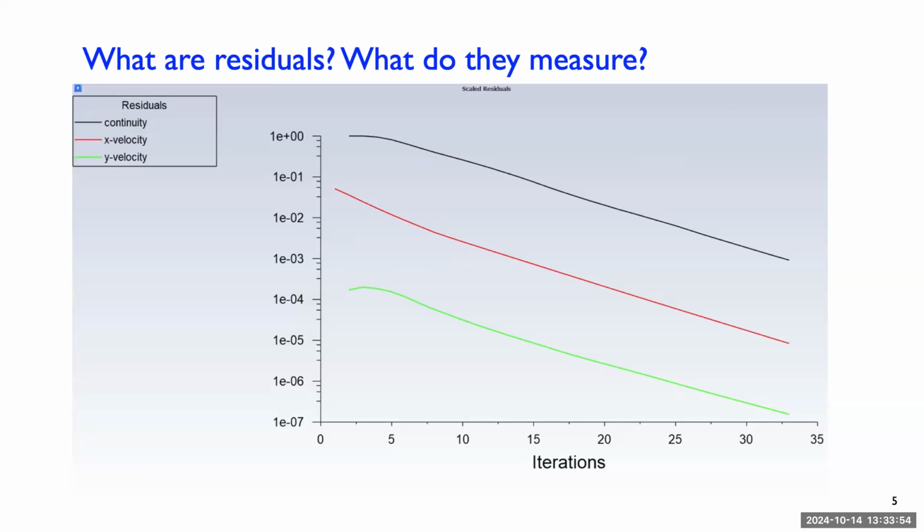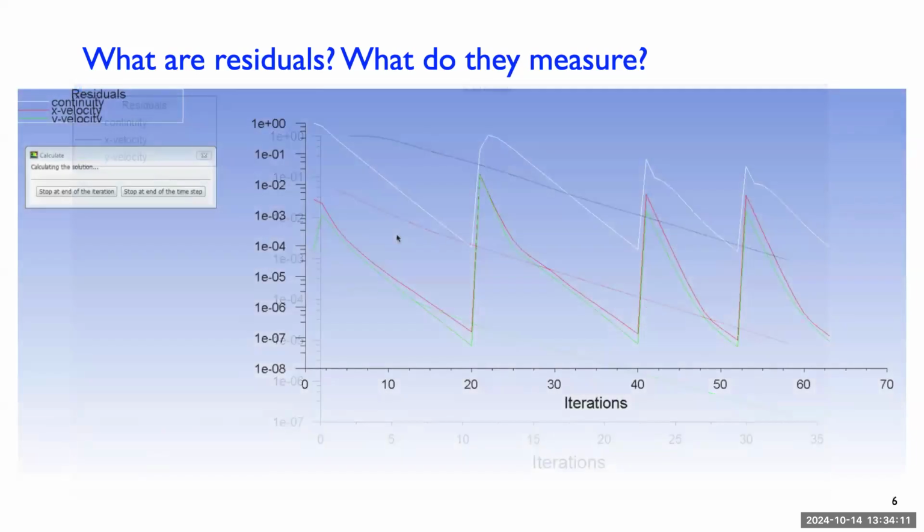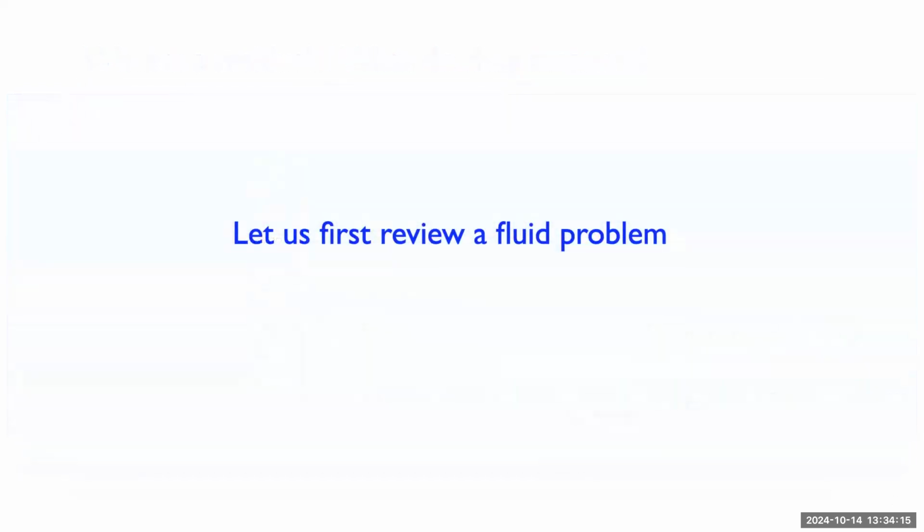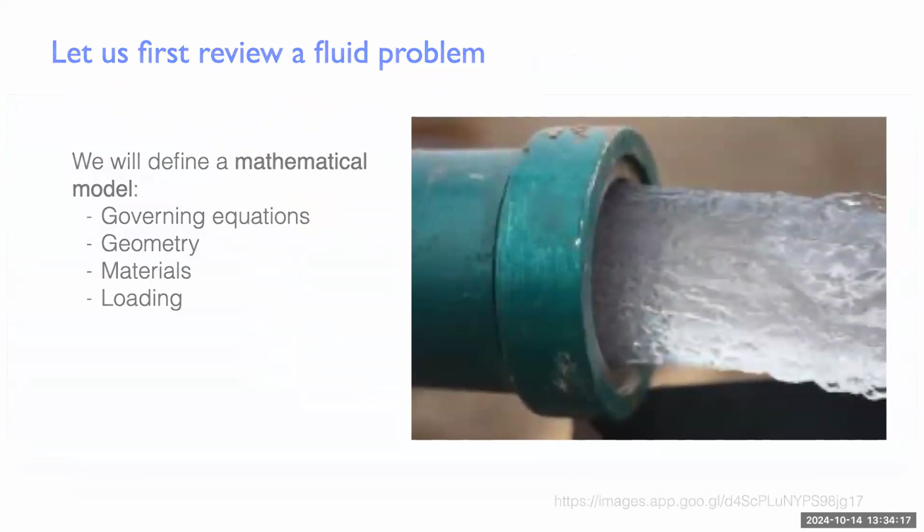So these residuals are the so-called scaled residuals. They're dimensionless. So if you run the problem small or big, if it's the same physics, just scaled down, it should show the same behavior. But this shows that these errors are not driven to 0. They're just driven to what should be considered small for this problem. And unfortunately, small for one problem may not be small for other problems.